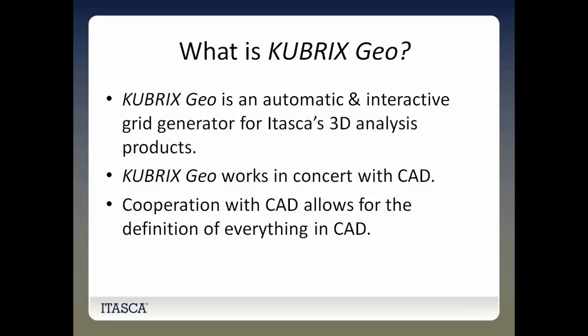And they have to be made to the geometries at a stage where they're most easily modifiable, and that is when there are surfaces, before they become zones or before they become blocks. And a good program to do this modification, obviously, is a CAD program, and Rhino is sort of our favorite because of certain accessibility and ease of use and cost. So cooperation with CAD allows for being able to constantly modify the geometry, then push a button and generate a new model.